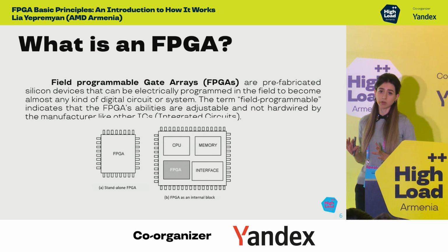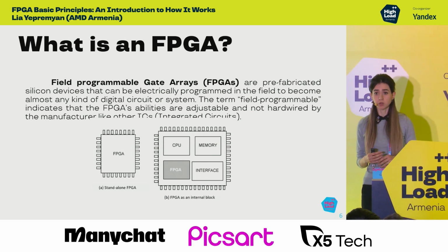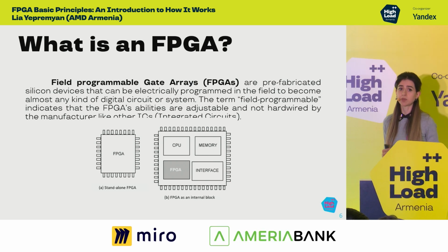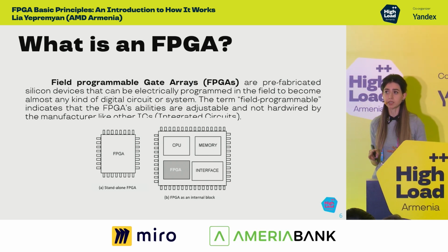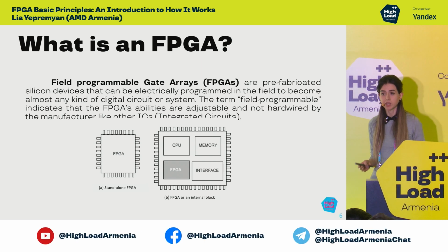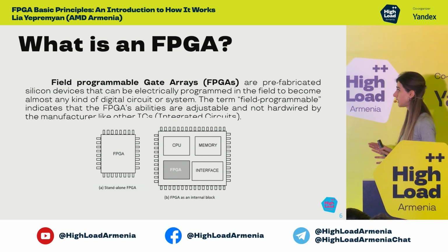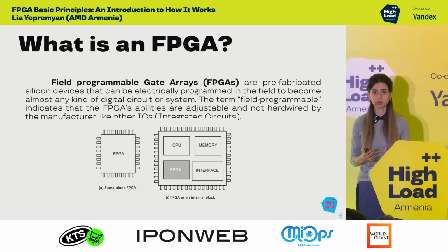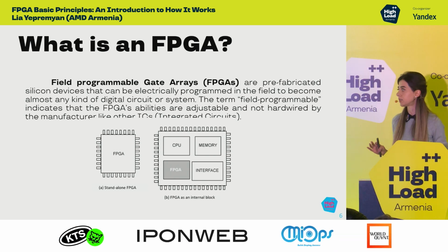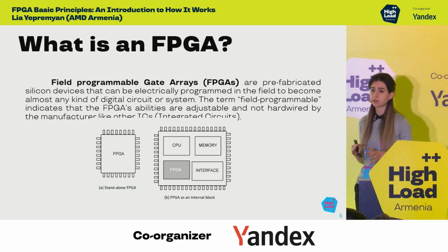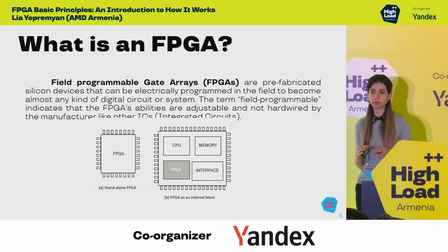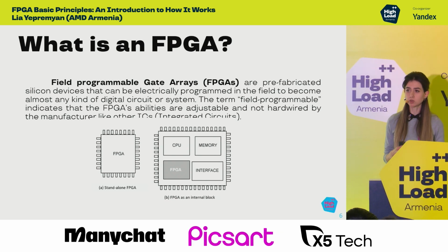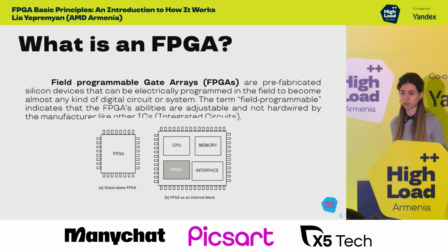So let's talk about FPGA. What is an FPGA? Field programmable gate arrays are prefabricated silicon devices that can be electrically programmed to become any kind of digital circuit or system. The term field programmable indicates that FPGAs are adjustable and not hardwired like other ICs. The fundamental functionality of FPGAs is built on their adaptive hardware, which gives us the ability to modify it after manufacture.